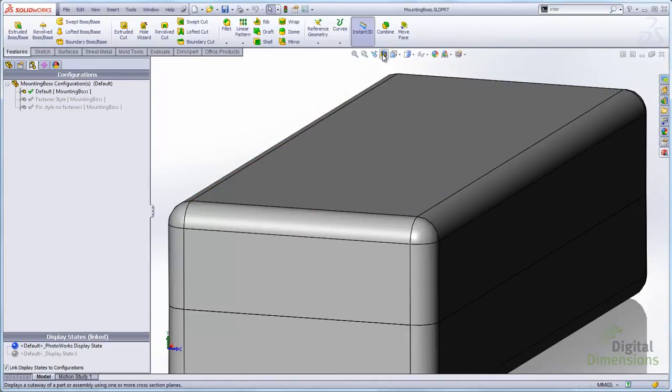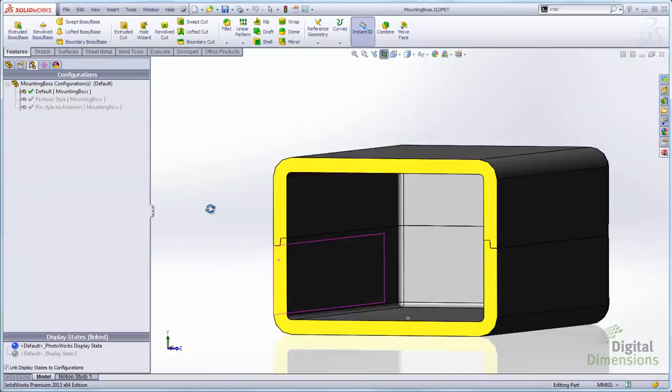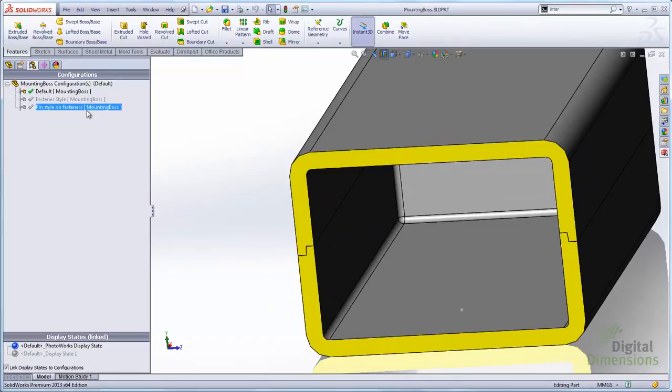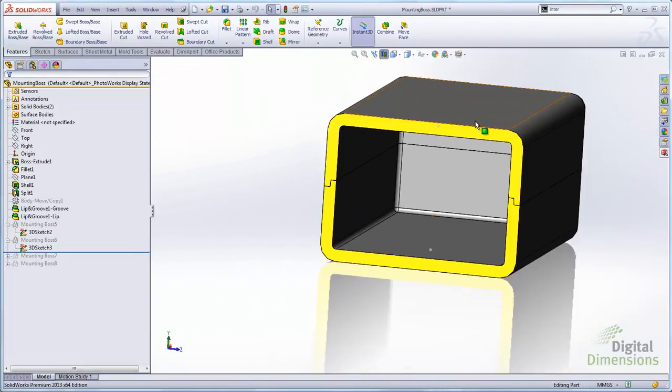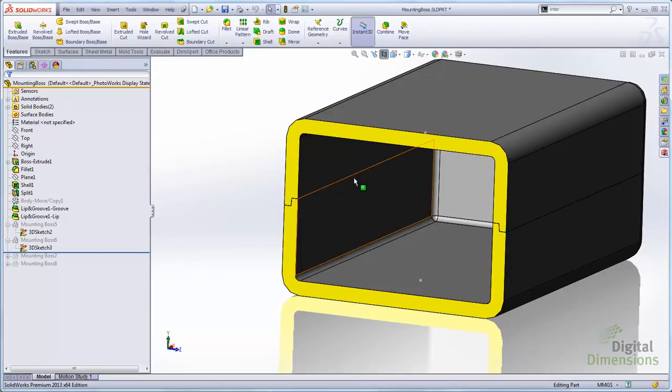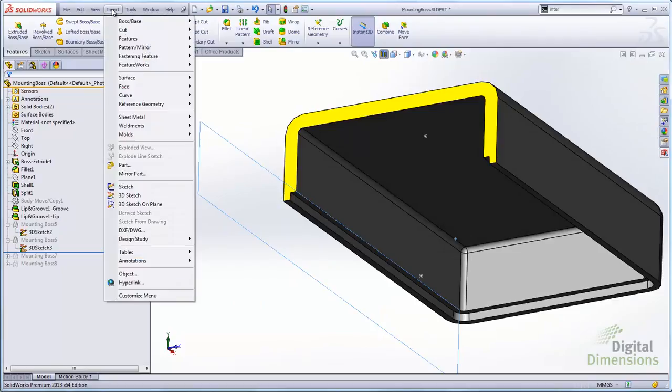So I just made a couple different configs to quickly show this. I've placed a couple points here to help speed this up. I'm going to start with the top section here. So if you've never used this fastening feature, it's part of this whole group here. One is called lip and groove, and I use the lip and groove to create the outside, this cutout here for that. So I use that too.